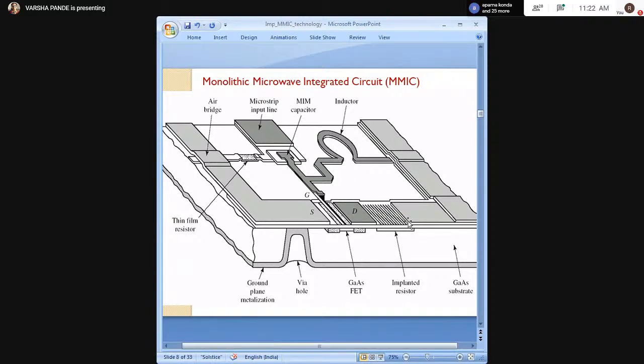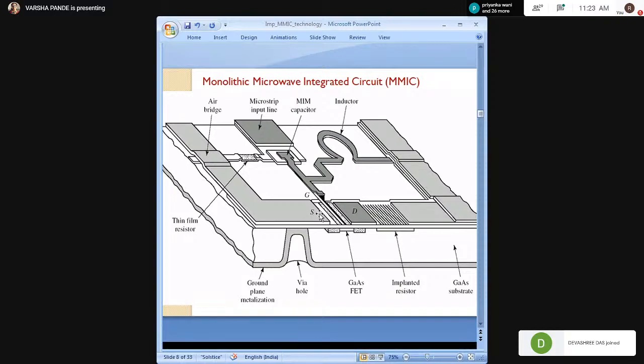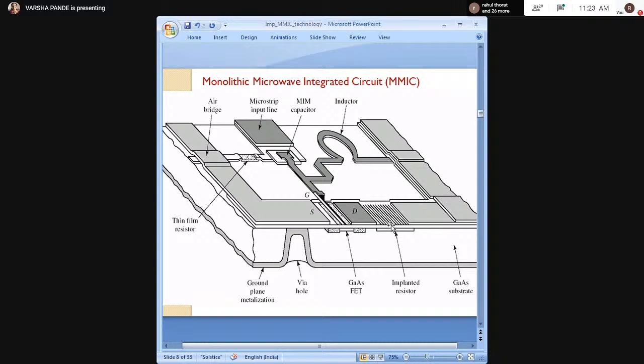For a resistive type we have to use resistive material, for capacitive, the capacitive material, like this. For a field effect transistor, the gate material is different, again oxidation will be there, suppose it is a MOS, then source and drain will be there. Then here again we have to add impurities, here the implanted resistor is there. For this we have to create a layer by layer structure. If you are creating one layer, the other area should be protected, and within that area only you have to implant it.